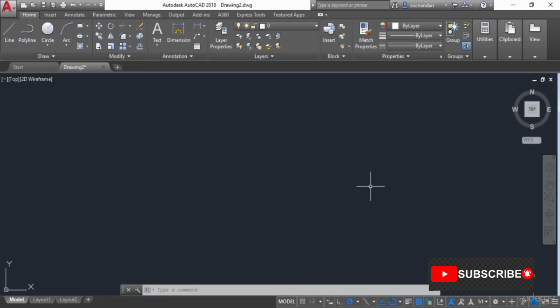So let's say that we want to make a simple line which is inclined to an angle of 30 degrees with a length of 5 units. There are a couple of methods for doing that as well, but we will use the simple polar coordinate method in this lesson. So let's start the line tool again, click anywhere in the drawing area, and now, as I told you, we need to make a line inclined to an angle of 30 degrees.